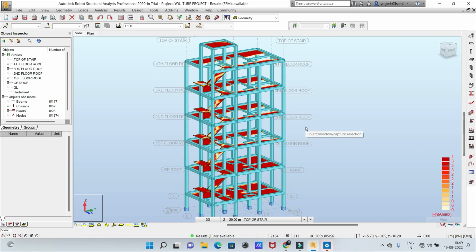Okay, so we'll be considering two types of load in this footing design. One is SLS, and SLS is considered for the footing size, and the other one that we'll consider is ULS, and that will be considered for footing thickness and also for checking the punching shear. Okay, so now we are going to see how we can first of all define the load combination.